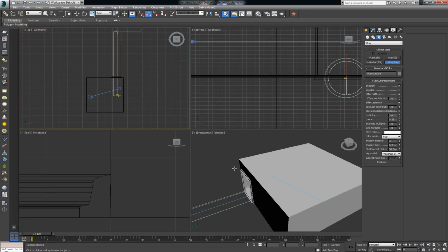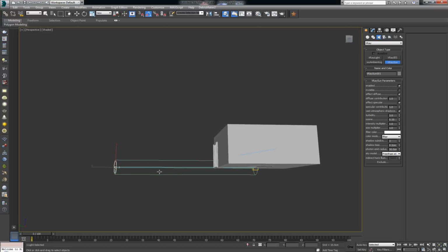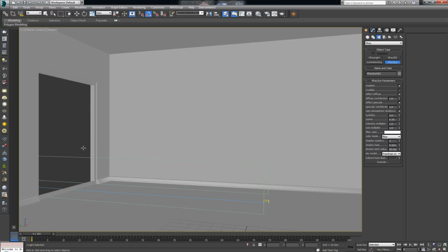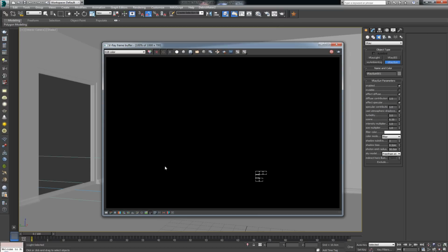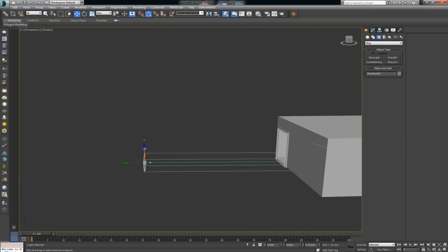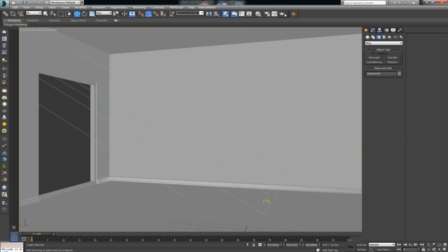And let's see. All right, in the perspective, this is the thing when you're using V-Ray Sun. Depending on where the sun is positioned, that's the amount of light it's going to be emitting. So for example, I've placed that V-Ray Sun in this scene right now, but if I render now, as you can see, really nothing is showing up. It's dark again. So in order for this sun to start emitting some light, I'm going to have to take the sun and lift it up on the z-axis. So let's get back to here and render now.